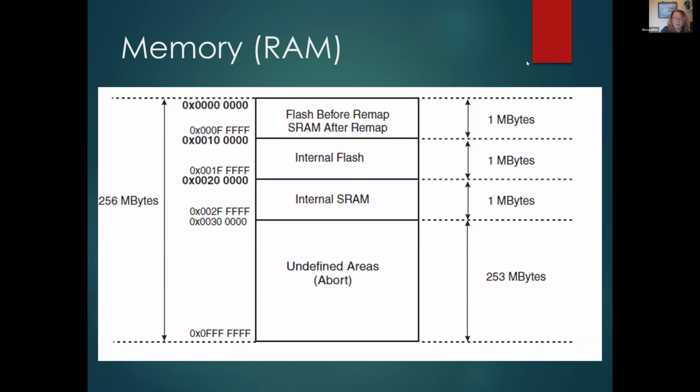And there are many techniques for optimizing RAM, but one of the most popular is to have a large chunk shared between 2 modules or objects. And sometimes the 2 pieces of code need the same data, but copying the data is slow and you don't have enough RAM anyway. More often, the 2 modules trash each other's data, taking turns using the RAM. And as long as everyone is polite, it works out fine. But odd bugs happen when both modules write to the buffer at the same time, interleaving their data with predictably disastrous results. I'm going to quietly back away from that mess, and you probably should too.